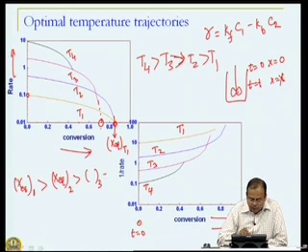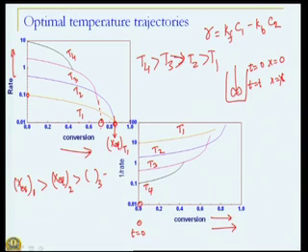What happens when the conversion is low? 1 over R is lowest with the temperature T4. So, let me just plot on the side time and what temperature gives me the highest rate or lowest 1 over rate. So, at the start, time equal to 0, the highest temperature gives me the lowest 1 over R. That means at the start my temperature should be T4.